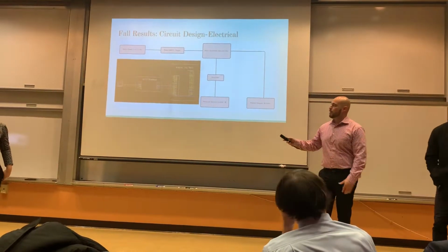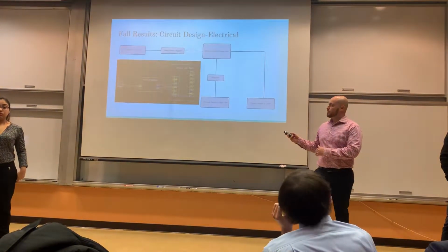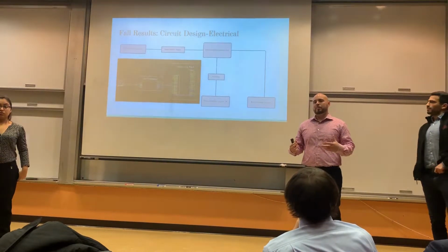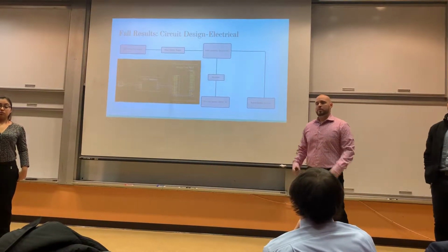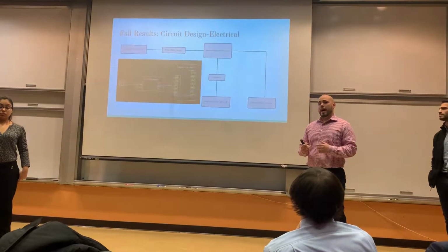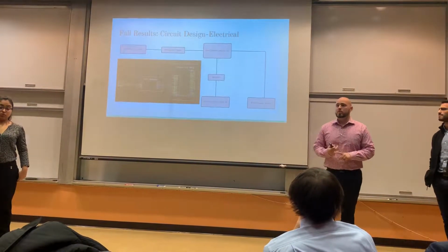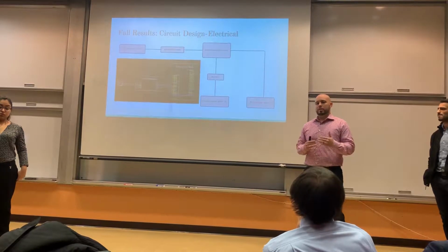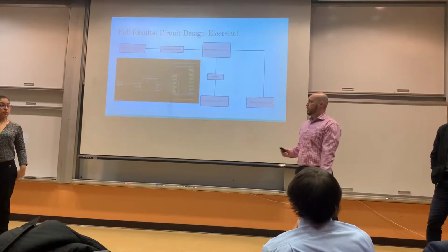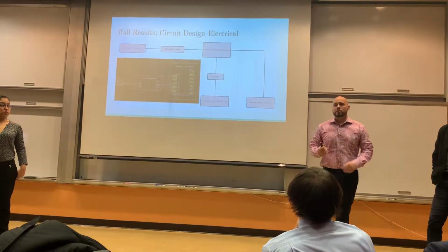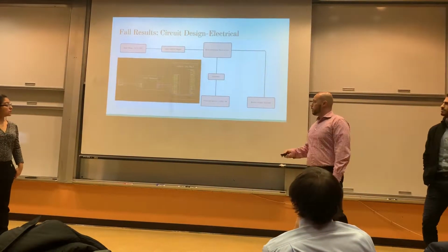In the black box at the bottom left, you're going to see our load cell that we've already identified on the left-hand side, and the wiring going to the HX711, which is going to be the amplifier that we identified that is designed specifically for load cell sensors. It's important to actually amplify the signal output from the load cell from millivolts to volts so that we are able to accurately read the change in resistance from that load cell. It is then going to be wired to the Arduino Uno, which is going to be recording our data for later analysis.